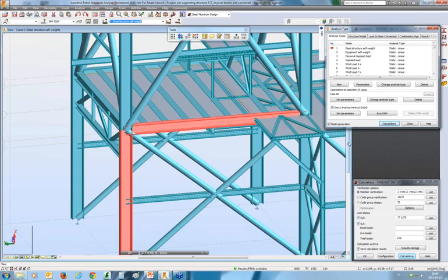This is, I think, a similar approach to European imperfections. So even for Eurocode, you may run this direct analysis method to compare the results with the traditional setting of buckling coefficients, using second-order analysis on the structure that is not vertical and has all the buckling lengths set equal to the lengths of the columns.